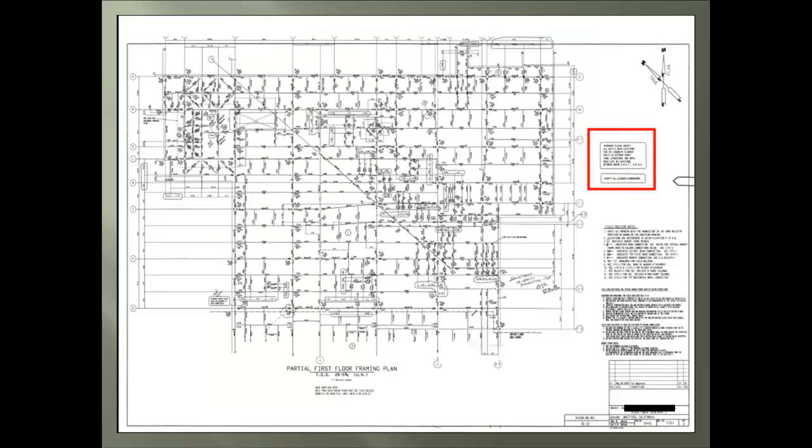Sliding down the sheet, we will look at these clouded boxes. Usually a clouded area means it's a change order or revision to the drawings, but in this case it's being used to alert everyone to a special situation. With the first clouded box, it's asking for verification of the area where concrete planter boxes will be placed. And the next is alerting all involved to verify all clouded dimensions.